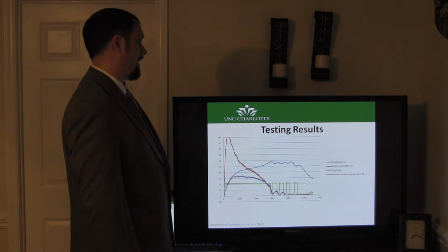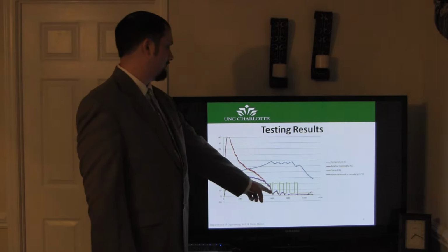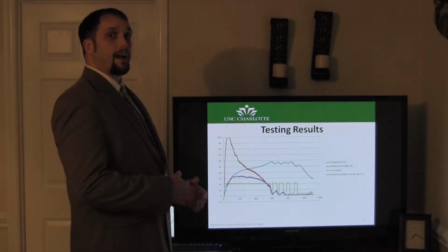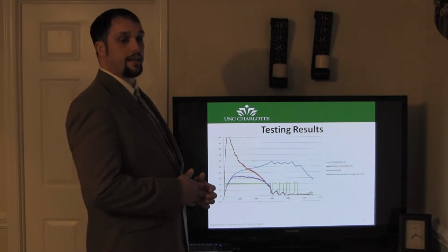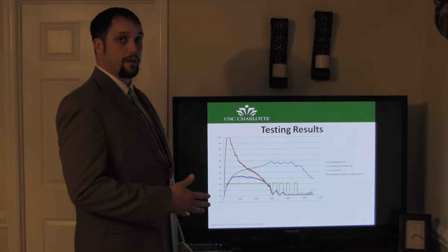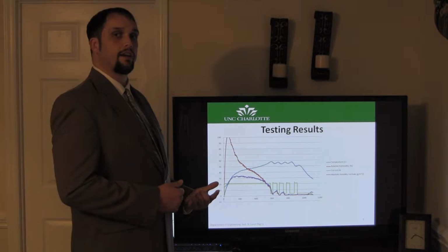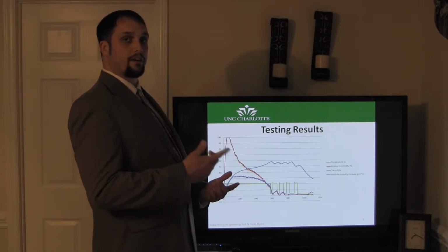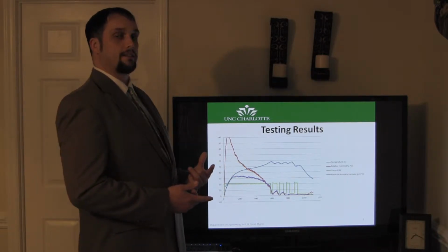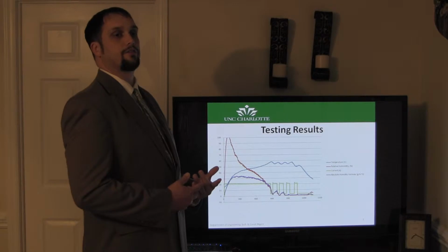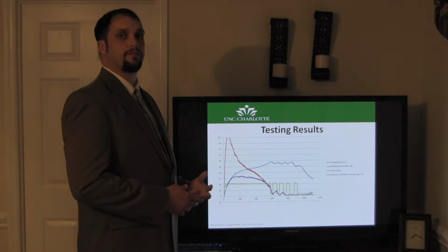So say you start at 5 and you end back up at 5. When you end back up at 5, you start a timer where the heat stays on for an additional 5 minutes. Once that 5 minutes has expired, you open up the relay that is providing the current for the heating element. Then you wait an additional 5 minutes, and then you open the relay that goes to the drum motor. So that totally turns off your dryer.